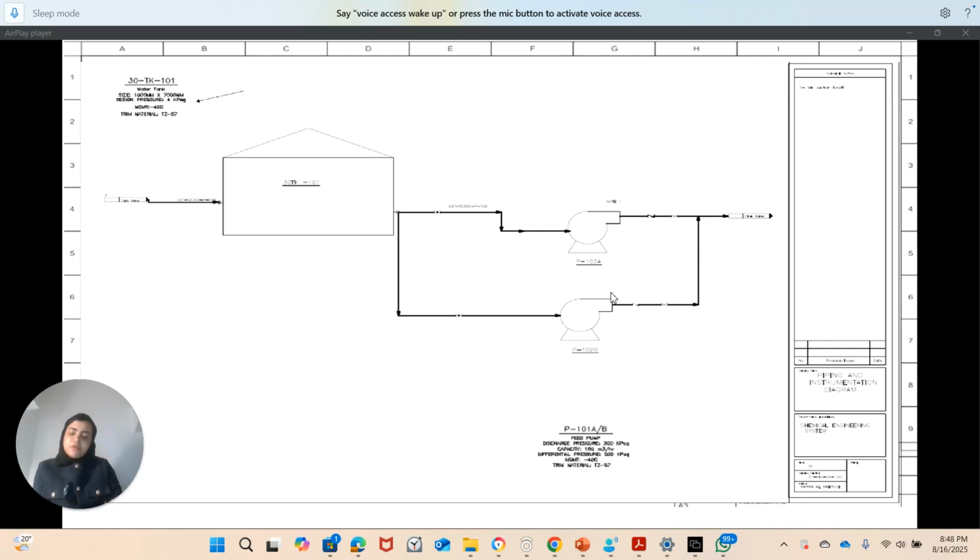So if you want to transfer this information to a process flow diagram, you should not transfer the mixing points and the split points, because this is not actually a capital equipment or any equipment. It's basically lines of pipes that will create this turbulence. So something like this here is a split point. In simulation it will be different. When you transfer this, it will be just lines.